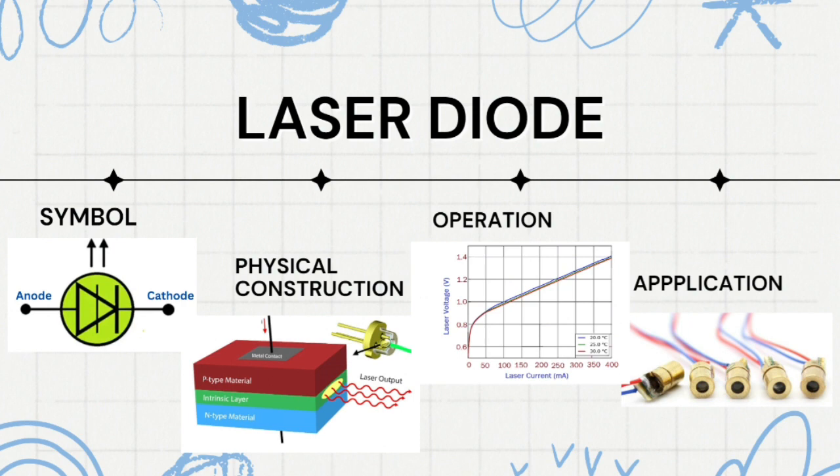In the forward bias region, where the anode is more positive than the cathode, the following graphic illustrates how at a specific threshold voltage the current increases dramatically, resulting in lasing activity and light emission. The threshold current rises as the diode temperature rises. The N-type and P-type layers are sandwiched between metal plates that are attached to the input terminals.